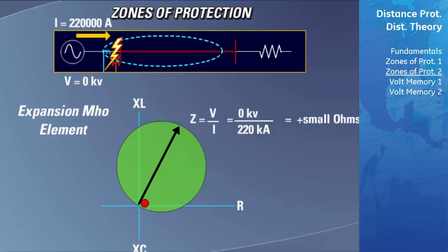To make sure that the mho characteristic does realize this as being an internal fault that needs to be cleared, the relay recognizes the low impedance of the line, sees that the value is positive, and enlarges the radius of the circle. Since the mho circle now extends past the origin to include a larger area, the location of the fault is sure to fit in the zone of protection, and the fault can be cleared properly. Notice that the reach of the mho circle does not change and still extends out to the end of the original zone of protection.